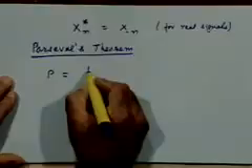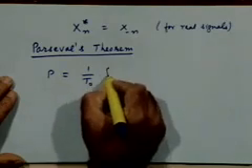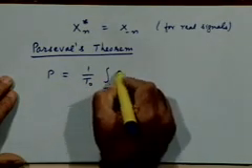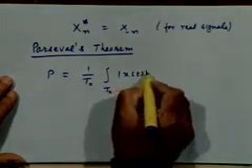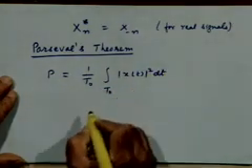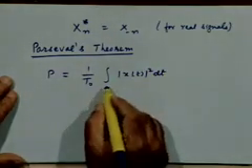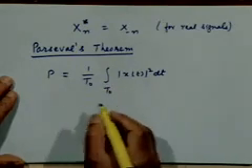So it makes more sense there to talk about energy rather than power, right? For sinusoids, and periodic signals in general, they have to be of infinite duration. A strictly periodic signal has to be of infinite duration, and therefore it is better described in terms of power than in terms of energy. So here we talk about power, which would be the integral of mod x of t squared dt over any period t0, divided by t0.